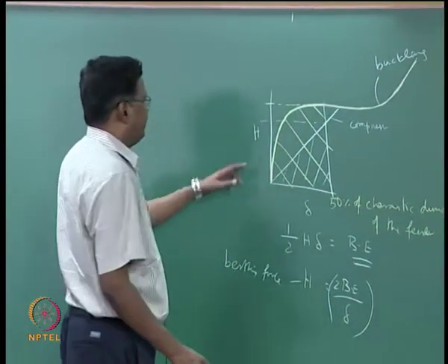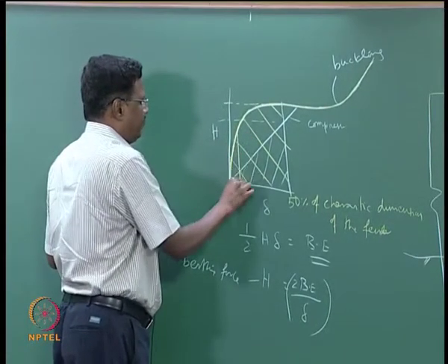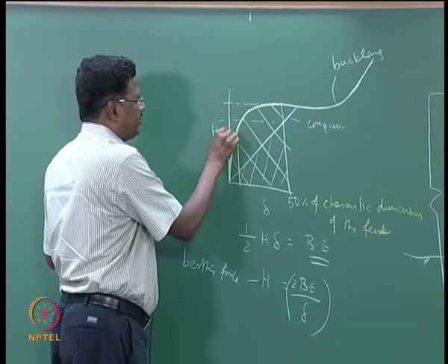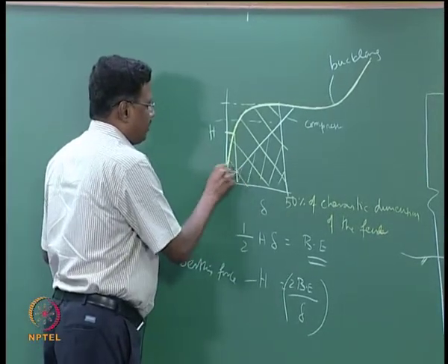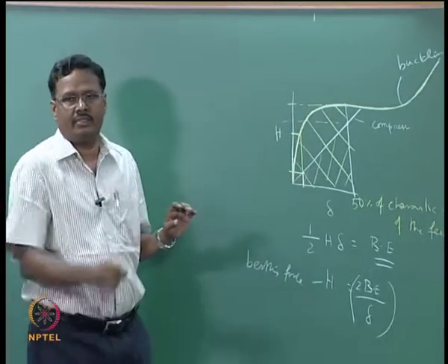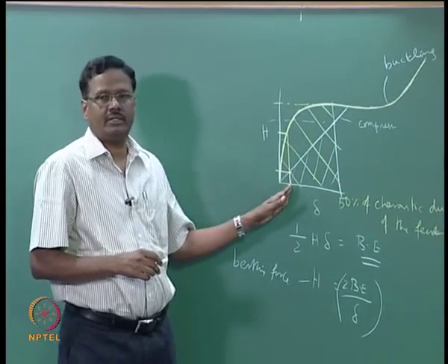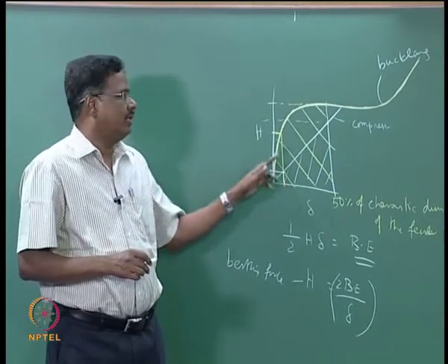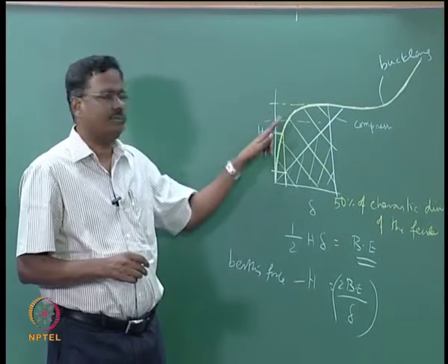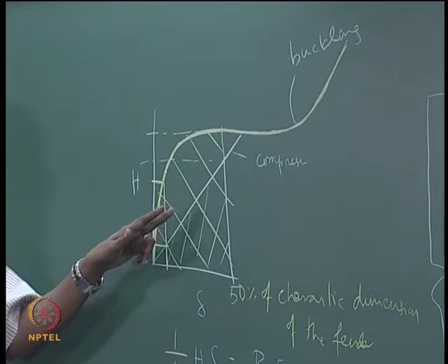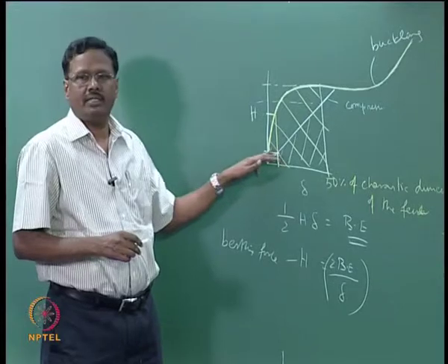One more thing we were telling is, even if the energy is small, suppose you want to take only this much deflection, the reaction is this much, whereas in this case for the other fender the reaction is less. This point is clear, this is what we are discussing. Even for very small deflection or very small energy to be absorbed, the reaction level will be very high, because this curve is steeper compared to this curve, whereas this fender we prefer for smaller vessels because the reaction will be less.